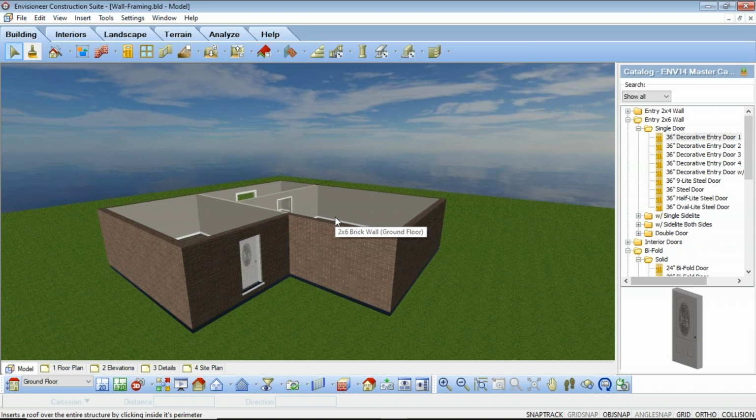The program matches the intersections in your project with intersections in that lookup table to determine how each intersection should be framed. Since there are so many intersection possibilities, intersections are defined on a per model basis directly within the model itself. The intersection lookup table simply retains the options you have chosen within a model.